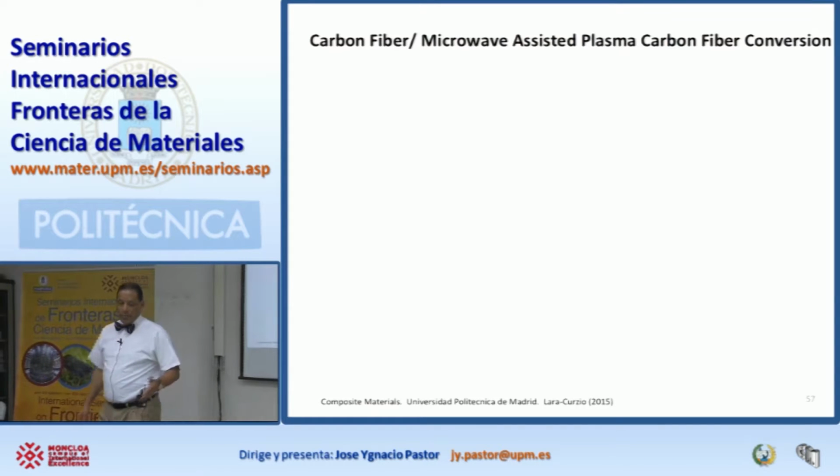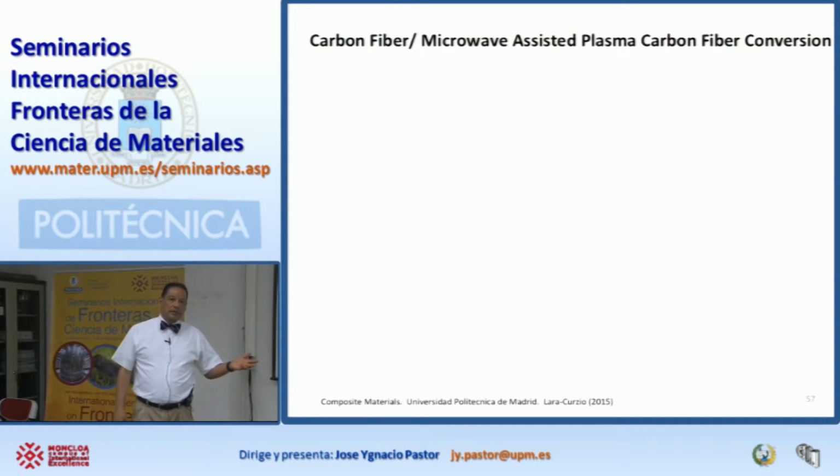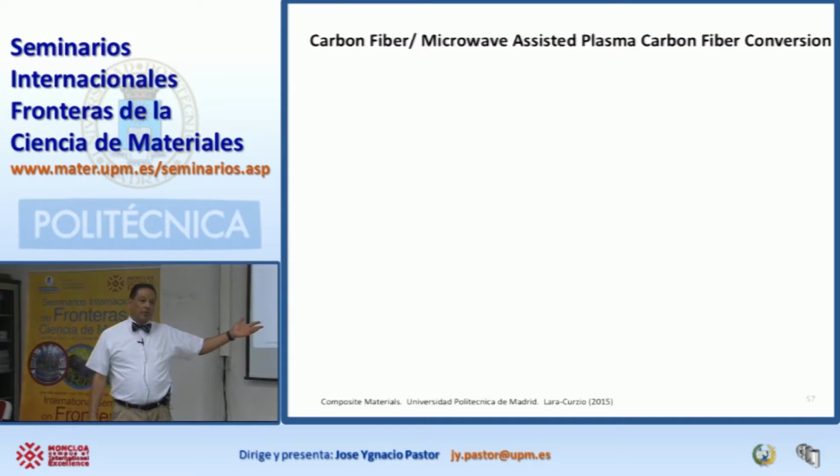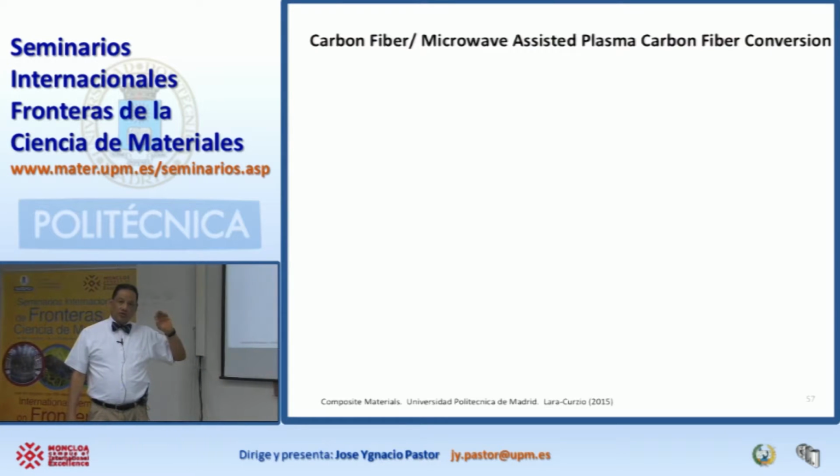And the reason why carbon nanotubes are even stronger is because of the Weibull size effect. The smaller the object, the less likely it is to find a defect. This is why the strength of carbon nanotubes is so astronomical. If you have a perfect carbon nanotube, the strength can be 100 GPa, which is an astronomical number.